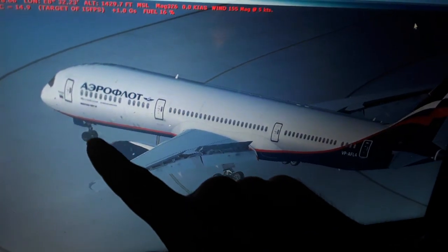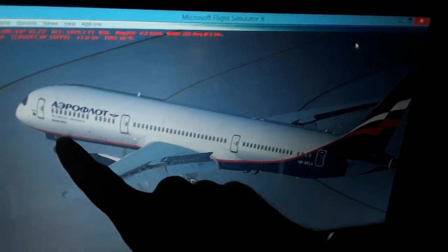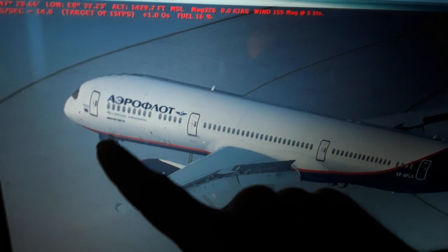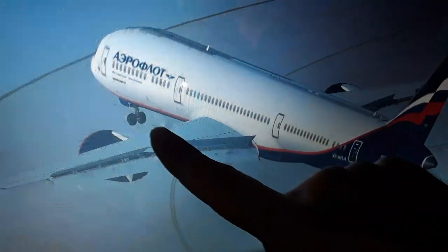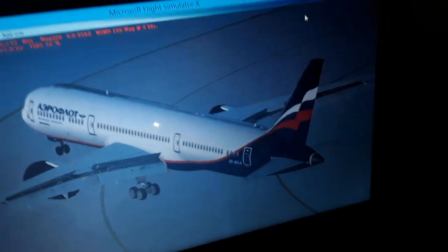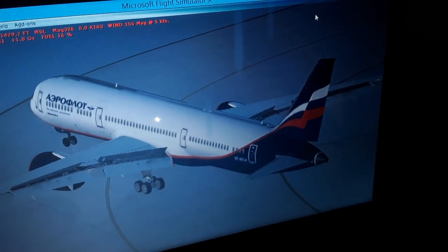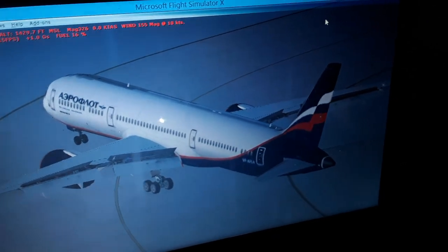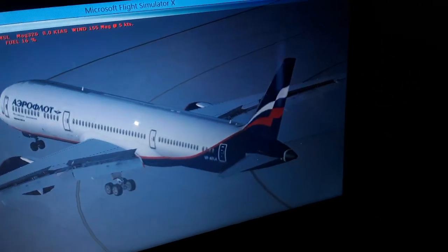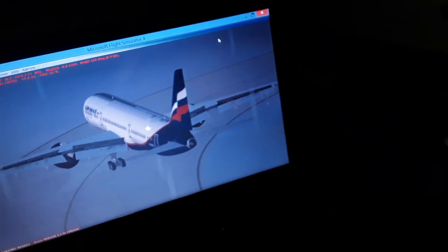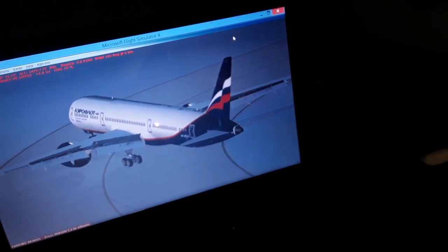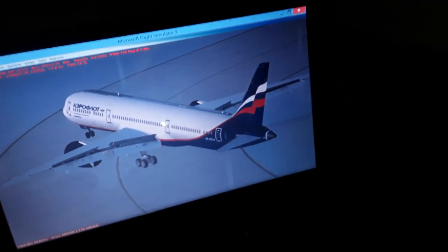Then above 80 knots, or 80 nautical miles per hour, 144 kilometers an hour, the forward nozzle is going to be locked from the computer at 0 deflection, or like 0.5 or 1 degree left and right deflection. So you have only the rudder for controlling the aircraft after that, from takeoff to complete the flight, then at the landing.